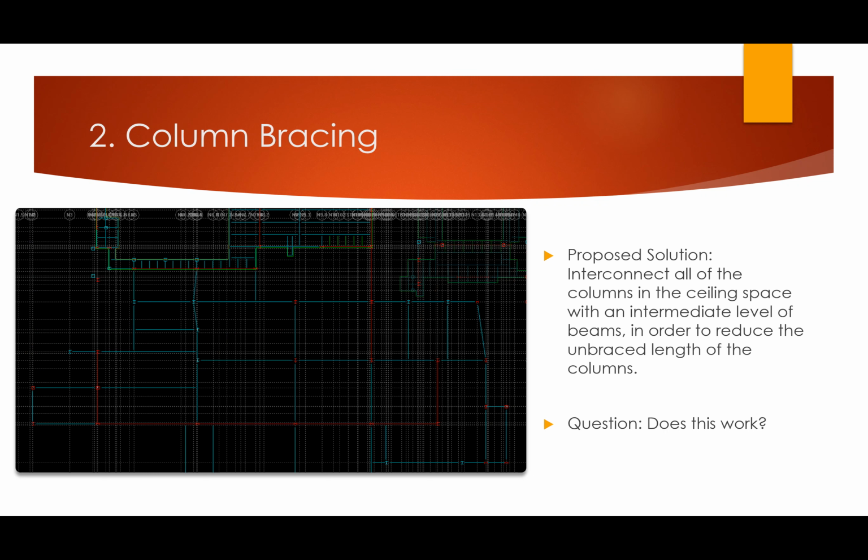And in fact, this is a snip from our analysis model when the engineer actually tried this. And interestingly, we run it, and immediately all of the stress ratios go way down. Everything works. Our columns went from a 1.6 stress ratio to a 0.8 stress ratio. Everything looks beautiful. It passes the column provisions. It passes all of the lateral, seismic, and wind provisions. Problem solved, right?